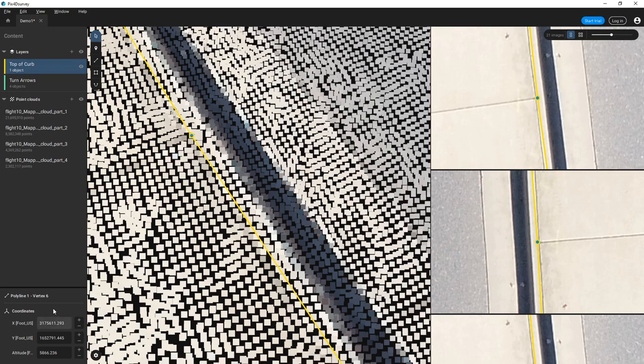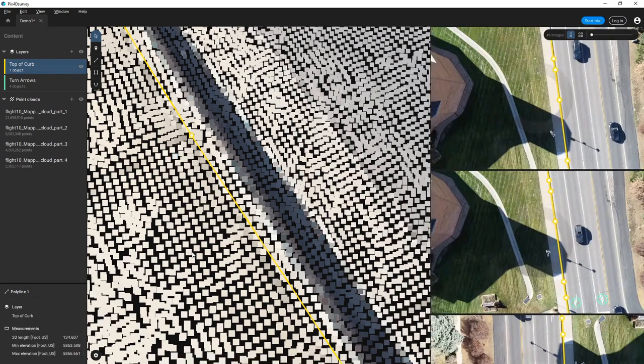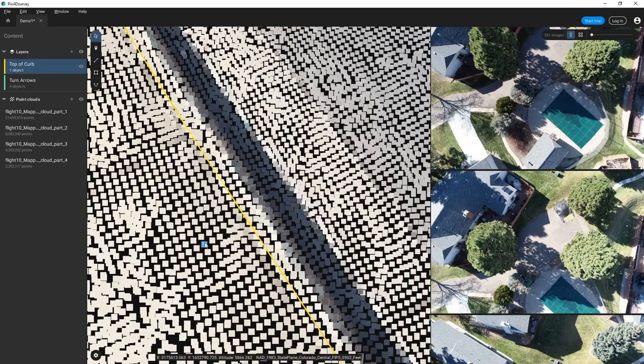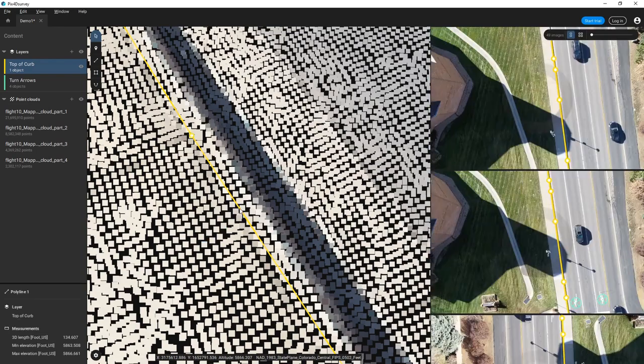However, you might have noticed down here, at this point when we have nothing selected, there are no properties down in the lower left here. But when we do have a piece of geometry, any kind of geometry selected, we get the basic stats for that. So you can see here it's a pretty flat curve, but it does actually show, what's that, 3 feet of elevation change.